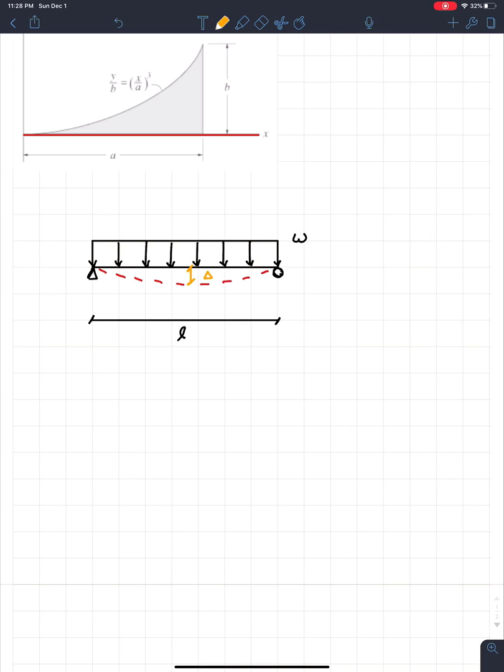But let's say that it deflects 30 centimeters. So our whole beam will have this giant arch in it, and people walking across won't feel very safe. The best example are those suspension bridges, the ones just for people that they have in the mountains. Everyone gets really scared when they start walking on it because it starts swaying and deflecting, and we don't want that. If you were driving down the bridge here in Edmonton and the bridge started going down as your car went on it, things would be pretty scary.